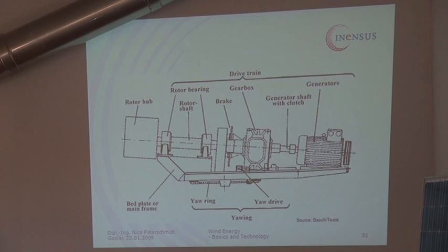standard series. The small wind turbines actually refer to the -2 series, like 61400-2. Large wind turbines are rather 61400-1. But actually both standards require the turbines to be fail-safe, and they need two different braking systems. And in this case, this would be the brake disc in front of the gearbox, a mechanical brake, and the second one would be the generator brake, together with the stall effect of the rotor.